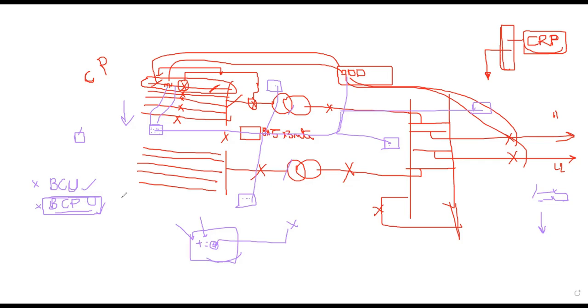So in one panel, we can accommodate two feeder protections. For the particular 33 kV, 11 kV, we can see two feeder protections in a single panel. You can accommodate it like this. This we will call a twin feeder panel. All the developers are providing this twin feeder panel.